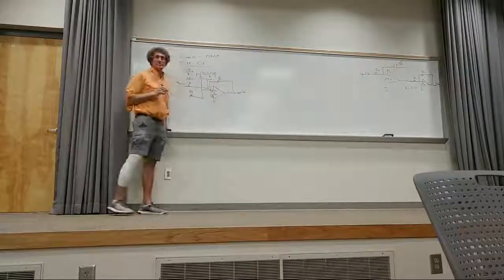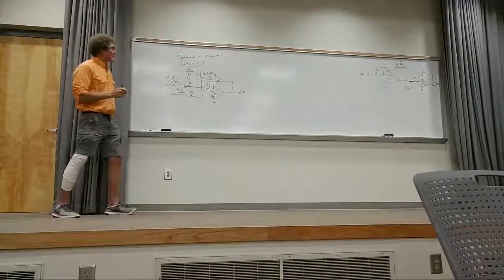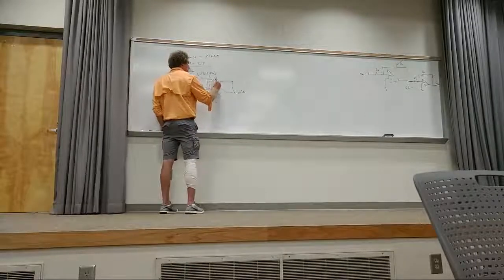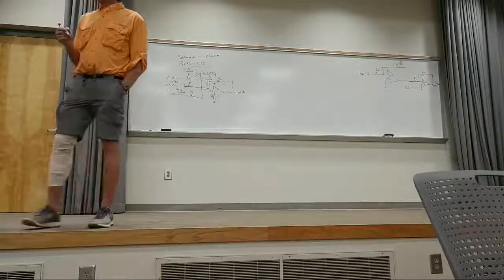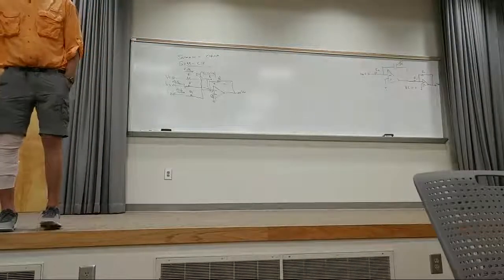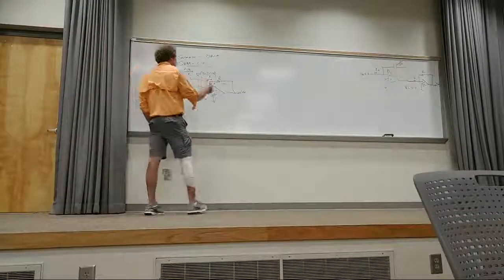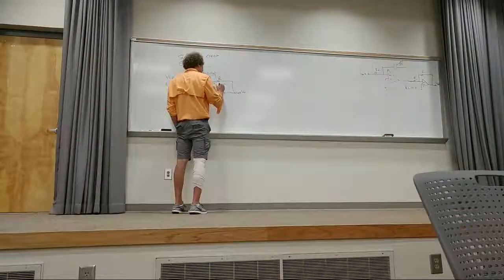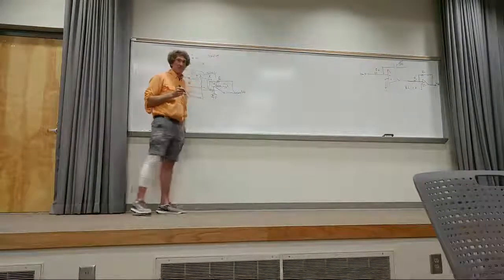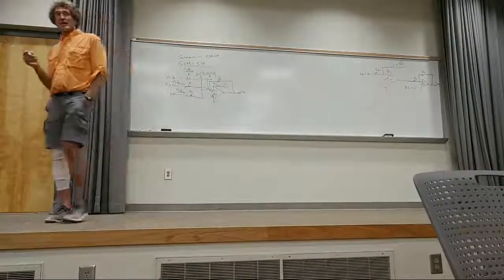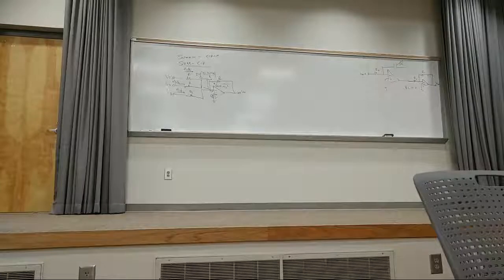Correct, class? All right, what's the voltage developed across this resistor? I'm going to put it plus to minus. Just think about it. It's that current times R, isn't it? What's the voltage? V1 plus V2 plus V3. You'll notice it's plus to minus. So the voltage here is just V1 plus V2 plus V3. But the sign is negative to positive, right? Everybody? Current times resistance is voltage. Current is V1 over R plus V2 over R plus V3 over R. Do you agree with that? Just multiply that by R, the R goes away, which is nice.